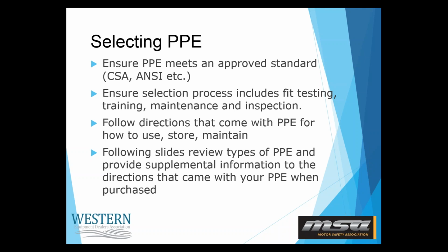And also ensure that when you are selecting PPE, you take a look at the whole process. If I'm purchasing different types of respirators every other year for my staff, how do I know that they fit? Because they need to fit my worker, and if they were fit tested to a respirator from one company and I purchased it from another company the following year, they're going to be different. So we have to have some consistency.